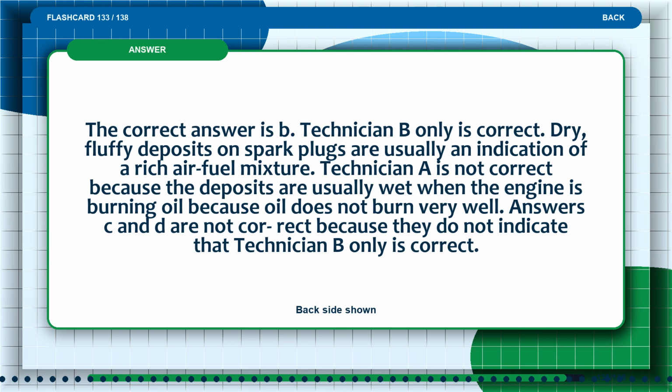The correct answer is B. Technician B only is correct. Dry, fluffy deposits on spark plugs are usually an indication of a rich air-fuel mixture. Technician A is not correct because the deposits are usually wet when the engine is burning oil, because oil does not burn very well. Answers C and D are not correct because they do not indicate that technician B only is correct.